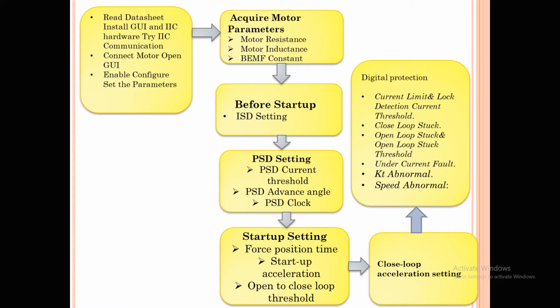So resistance, inductance, and motor velocity constant values will be totally different. We can't keep each and every data matched with the previous motor. So each and every time we design a new motor, we have to select the motor tuning parameters that will support that motor, and that's more or less related to the performance of the motor, how you actually want the device or motor to run to get your desired performance. That's the reason why we need to tune each and every individual motor.